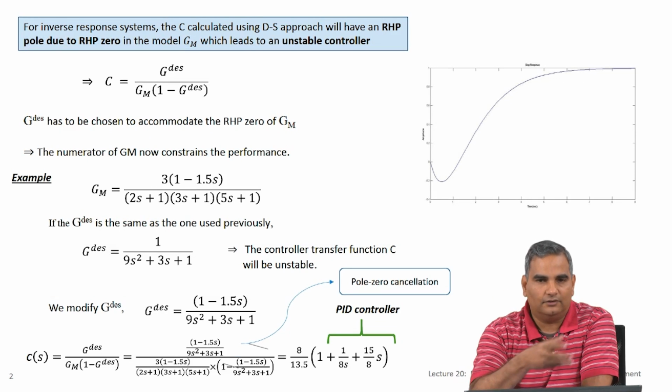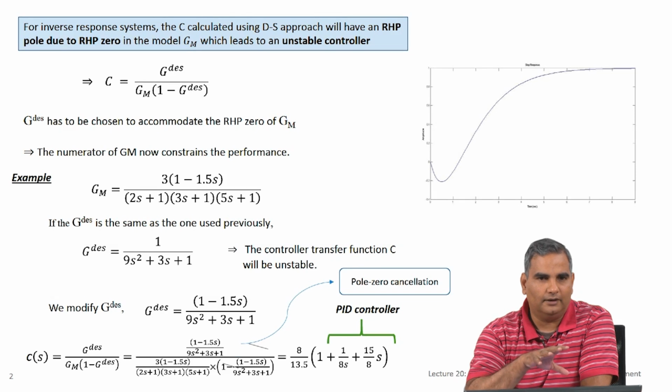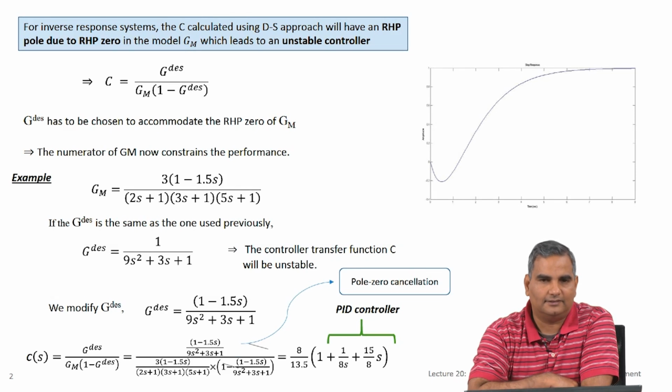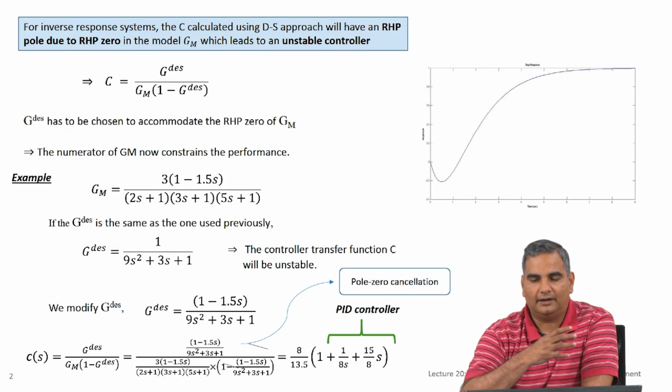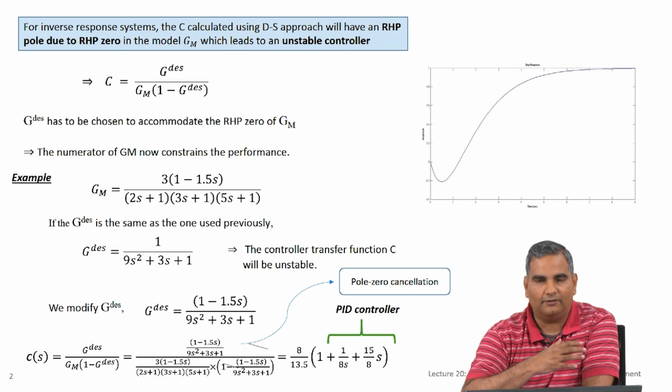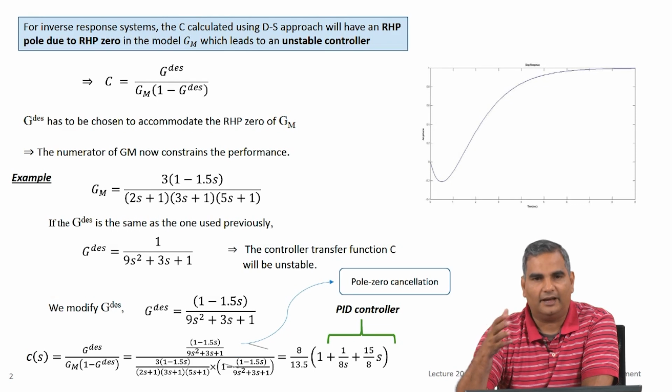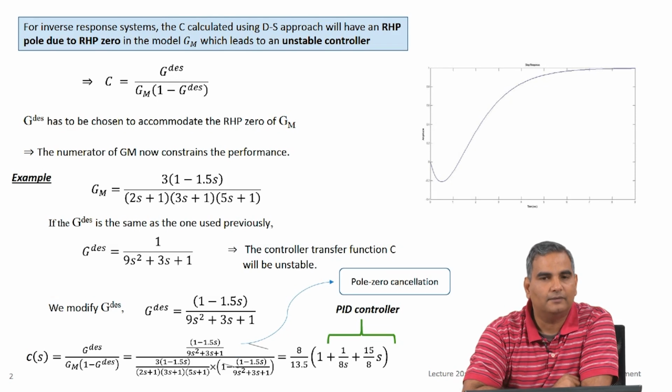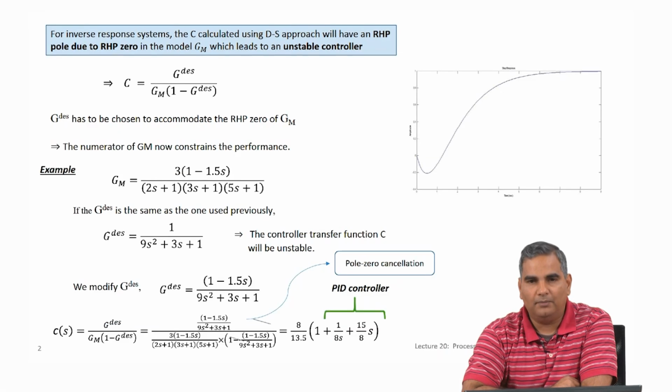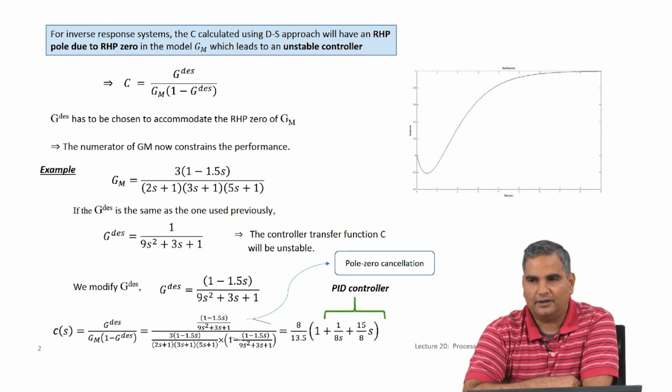Now, that is not possible, both mathematically and physically you can see this. So, another approach might be understanding that the system does have inverse response. What you could simply say is, okay, I know that when I turn right, I have to be completely turning right at all times as a G desired transfer function is not possible. So, maybe what I should do is say, okay, let me make a compromise.